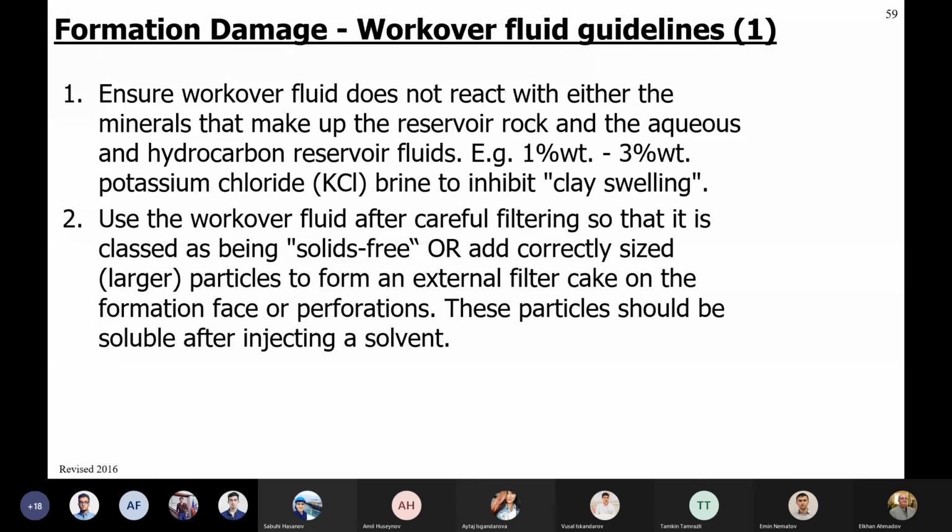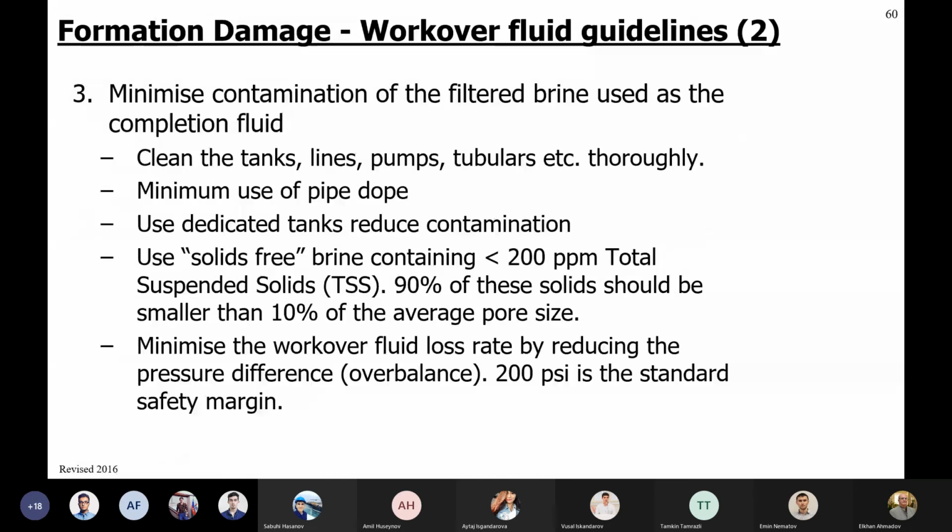To minimize contamination of the filtered brine, use completion fluid during the workover, and the tanks that contain those fluids should be clean. Lines, pumps, tubulars, everything should be cleaned from time to time, and after each workover operation.